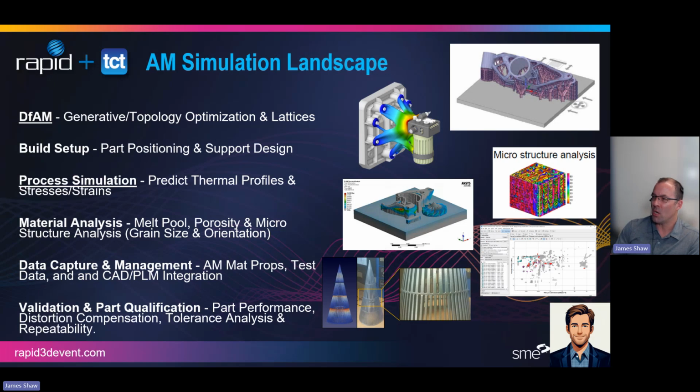And these tools are new because although we've had some optimization tools for a while, and as a design engineer, I won't call myself a design optimist, but now that additive allows us to manufacture geometry with a lot less restrictions and limitations, we have, say, this optimized topology design for this bracket we see here that is actually manufacturable, right? We can't CNC machine that. It'd be very, very difficult to say plastic injection mold that, forge or cast, right? Unless we were to try to abide by some of the draft angles and parting lines, et cetera.